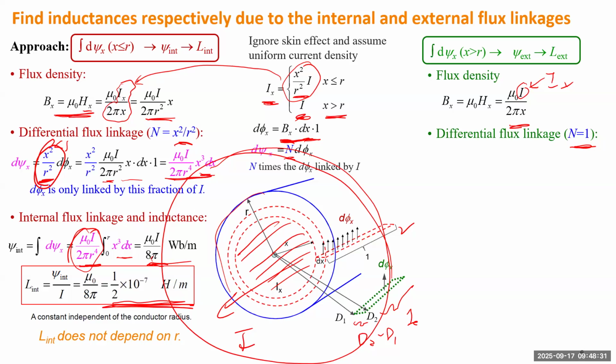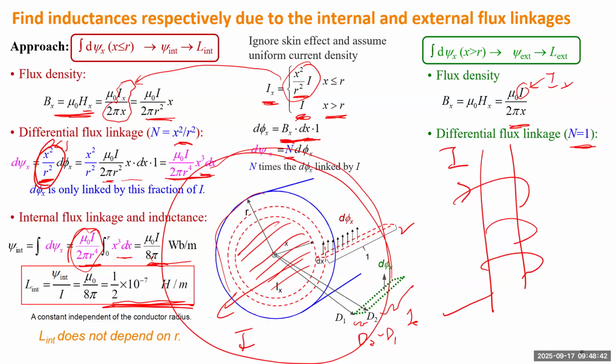Does everyone follow this? That's the only difference between the two sides, right? Let me explain this one again. Think about a transformer. This is current I, and there's N equal to 3. If the flux inside this leg is phi, the flux linkage is basically just 3 phi. Is this clear?